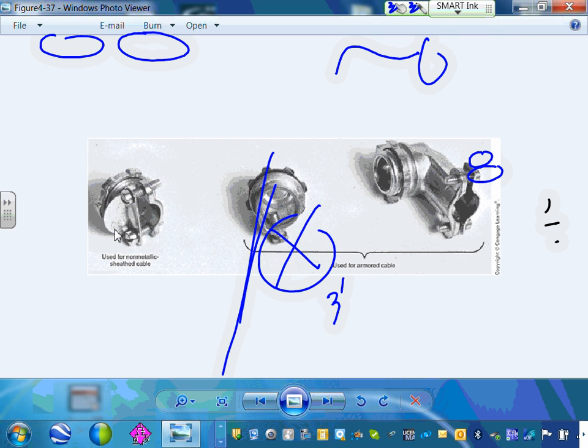Different hardware comes with the connectors. I always tell people the hardest thing, guys, about wiring is knowing what hardware goes with what. It really is. There are so many of them. For example, you have a connector for this and a coupling for this. The connector that works for EMT does not work for PVC. Even though they might fit, you put them in, they fit, they're a violation of the code. When you staple this into the wall, you might not have the right stapler. That one works with that, but not the other. So how do you know? It's all the hardware that goes with it.